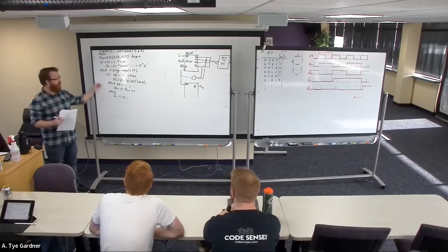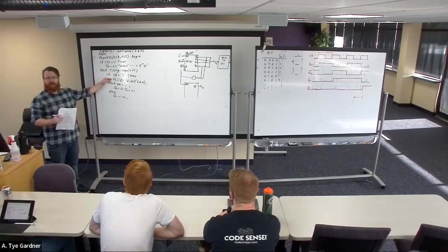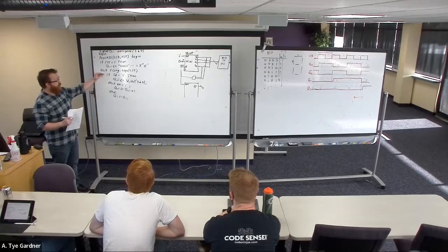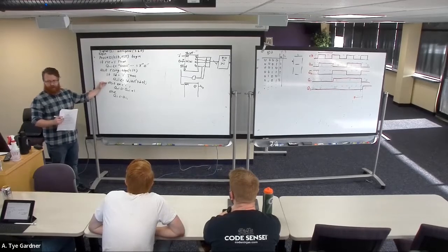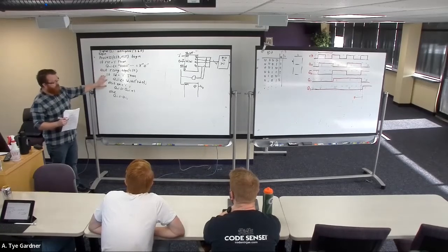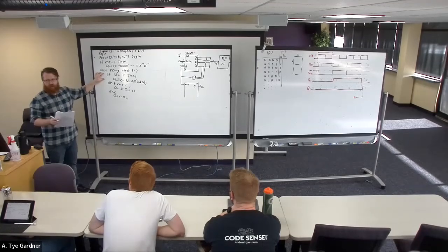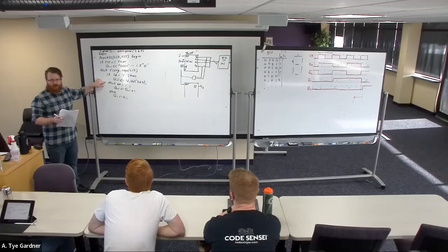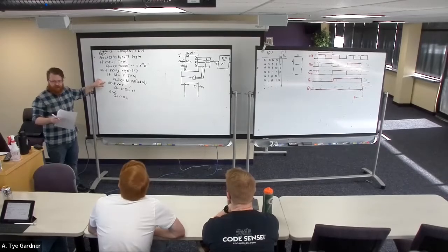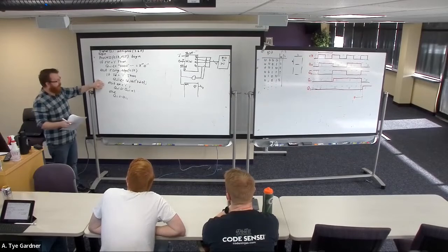It just stops. It goes, if this is true, okay, let's do it. It only says if this is true, no, okay, then we'll do this. So when this load evaluates, even if enable is on, it's not going to count up. It's just going to load. It's not going to load and count. It's just going to load because this is an else. Make sense? So the order of your if statements matter. So be careful with them. Think about the steps. Walk them through in your head.